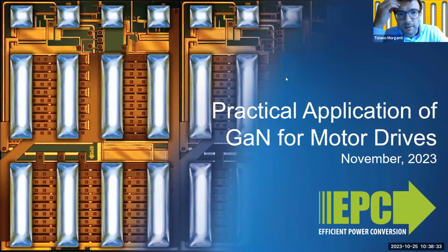Well, this is pretty simple, because the power consumption of the digital ICs, CPUs, GPUs and AI processors is increasingly high. So it's in terms of power, hundreds of watts. If you want to bring hundreds of watts on a motherboard, if you do it at 12 volt as in the past, it's going to be a lot of current. So a lot of current means a lot of copper and a lot of power loss between the main power supply and the motherboard.